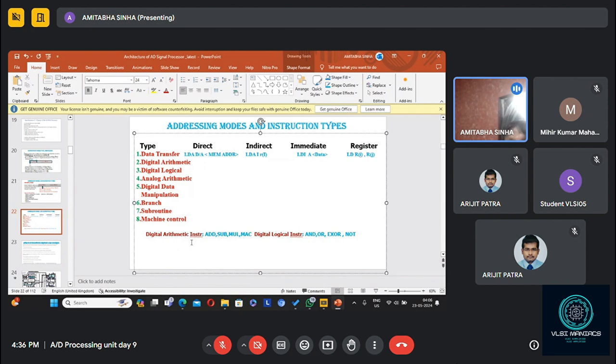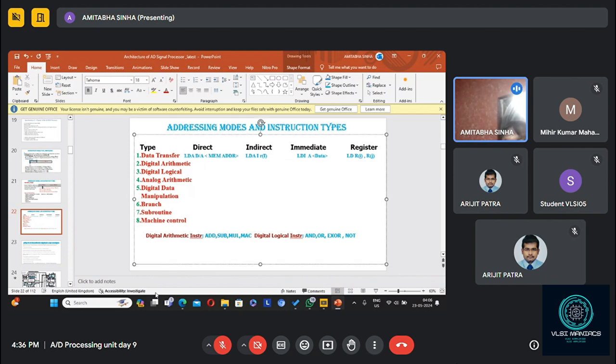When that value reaches 0, or if you start from 0 and it attains a particular value, your CPU will go to a subroutine. Where it will go can be indirectly done by setting a register's contents with some value. These are called software interrupts.